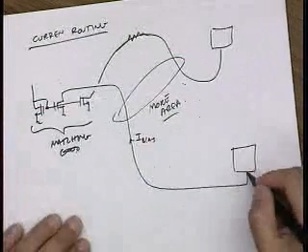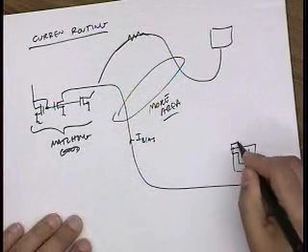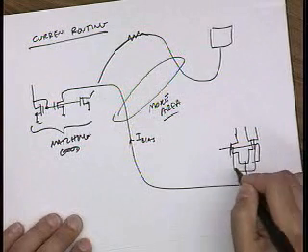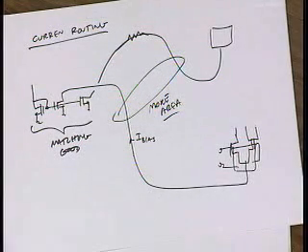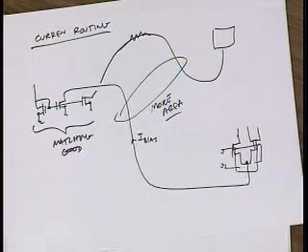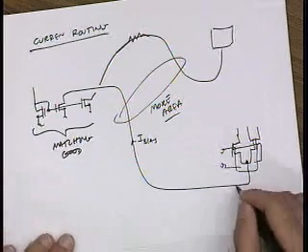Well, think about it this way. Let's say this is a diff pair. Okay. Noise from where? Your current source, your current's not clean, so that gets modulated to the output through the... Okay, that's a potential problem. I was looking for something else. Do you lose current through the capacitance in the wires? It's a DC current, right? So it shouldn't really be a problem. But you're onto something.